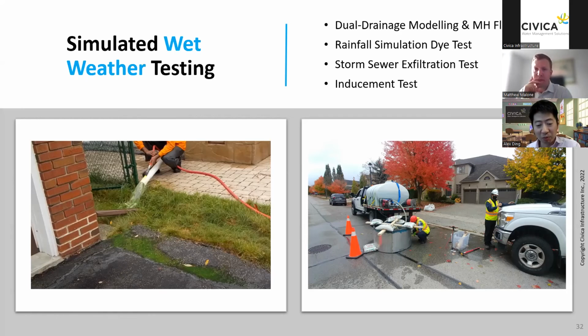Basically, you build a bulkhead around the manhole and start to build up the depths on top of the manhole lid, and we have a little device within the sanitary manhole underneath the manhole lid, obviously, to measure the amount of water getting into the manhole at this location. So you basically develop a site-specific capture curve.